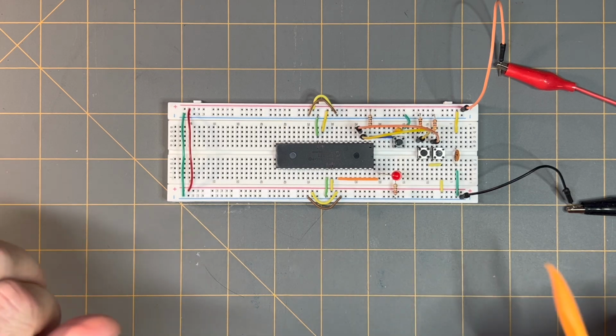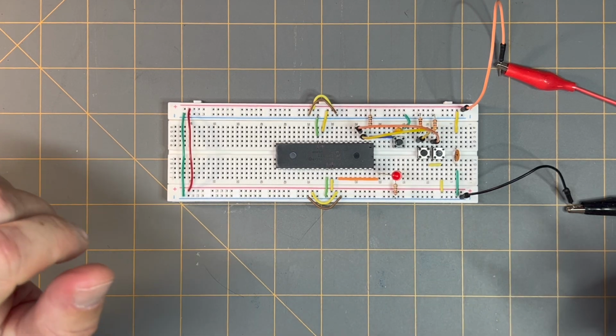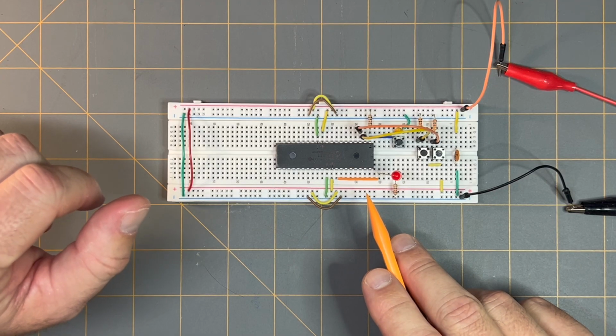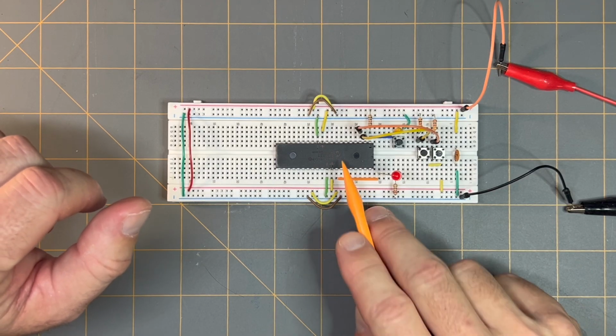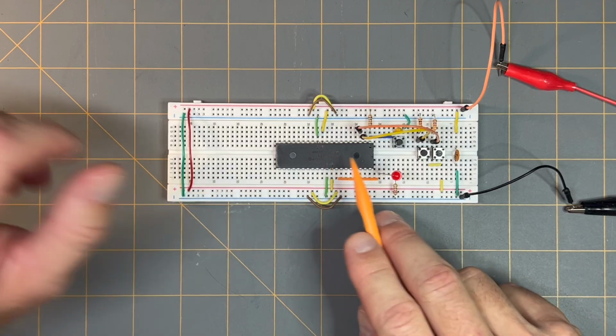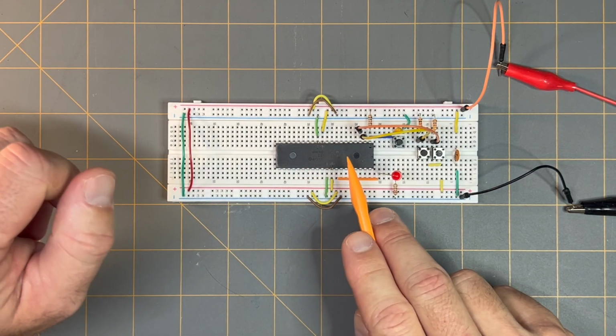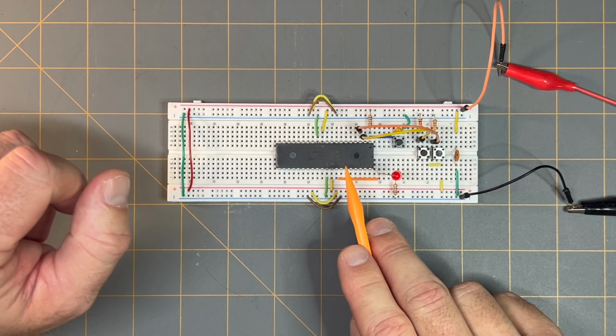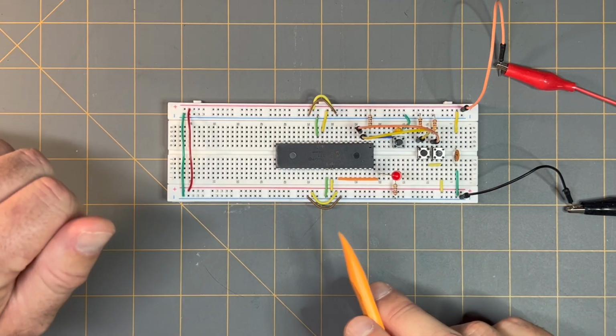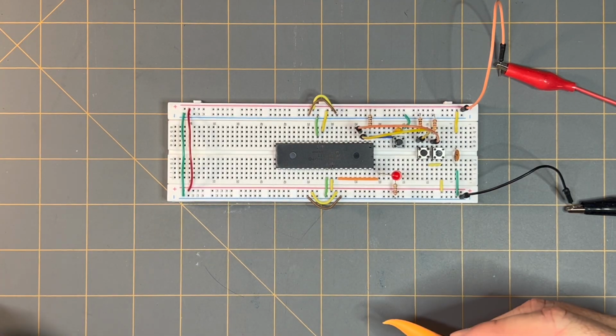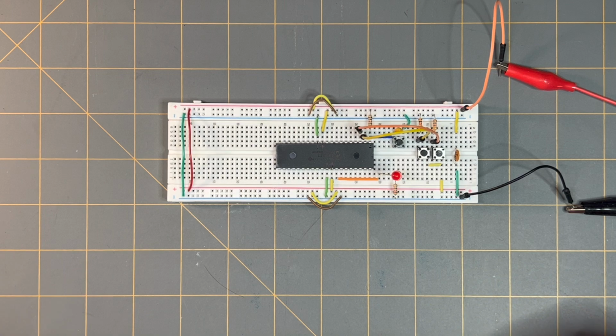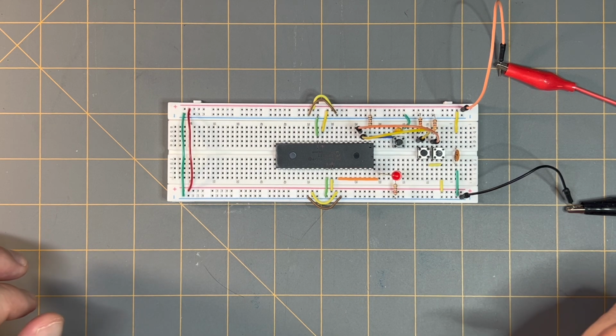So once you've gotten the code, compiled it, and loaded it to your microcontroller, you can place the PIC back onto the breadboard circuit. Make sure that you've placed it into the correct points. Then all there's left to do is just turn the power on to your circuit. And then we can see if everything's working as it should be.